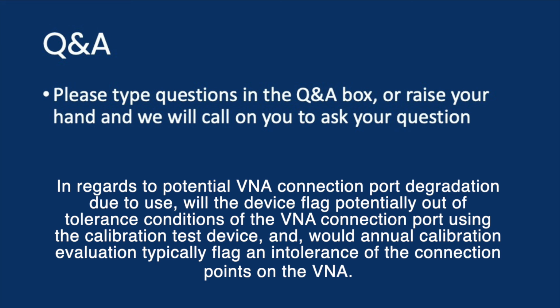We also have a new feature too that allows you to make measurements basically with uncertainty limits according to national traceability standards. So you put your device under test on the instrument, and depending on its loss and its reflections, you'll get these uncertainty bars around the measurement trace that will tell you if you're within spec or outside of spec.